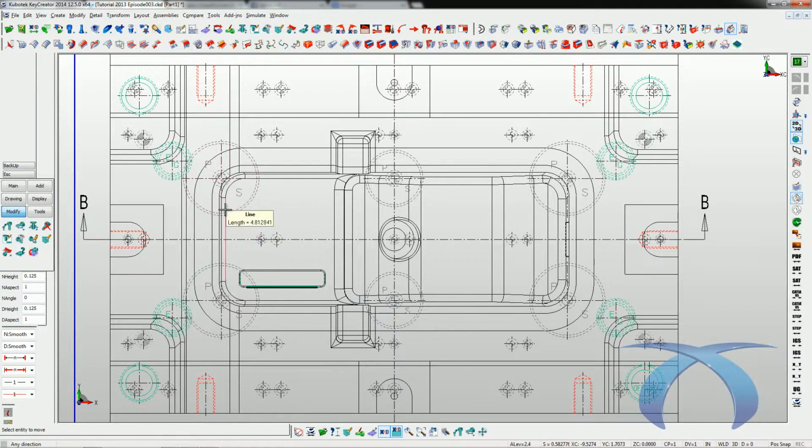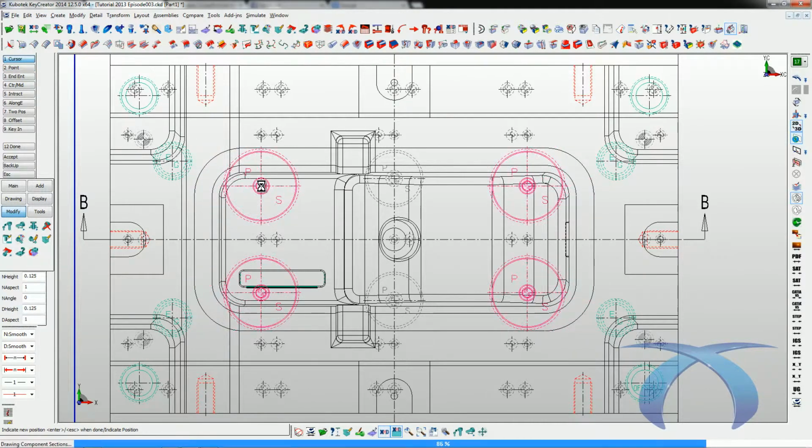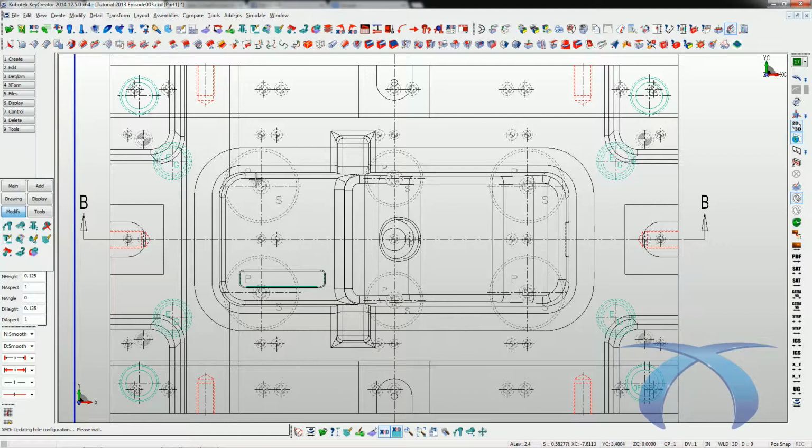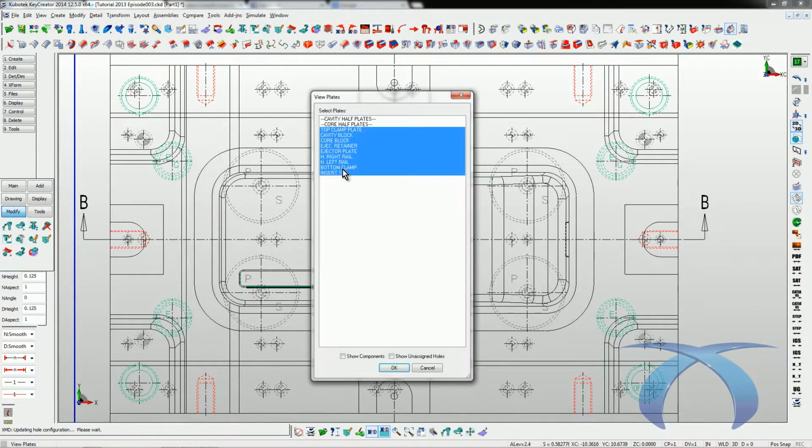And then I can also use the same thing for the move command. So if I go in here, we have a move command with several options. I can say in any direction, select this pillar support, and once again I can choose by group, and I can place them wherever I want, and you can see those 4 only moved. So I have the ability to manipulate things based on these quadrants, and it allows me to keep things symmetrical if need be. Very, very easy to work with.